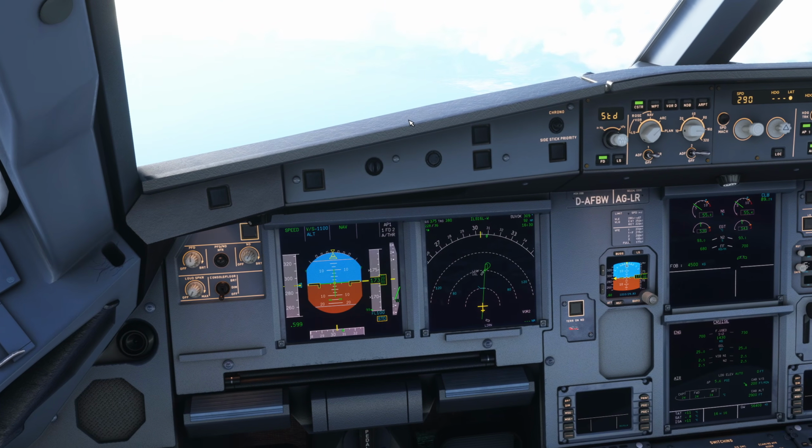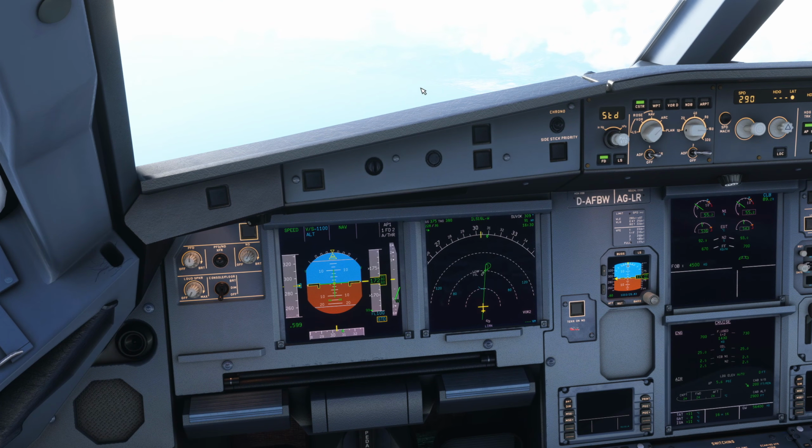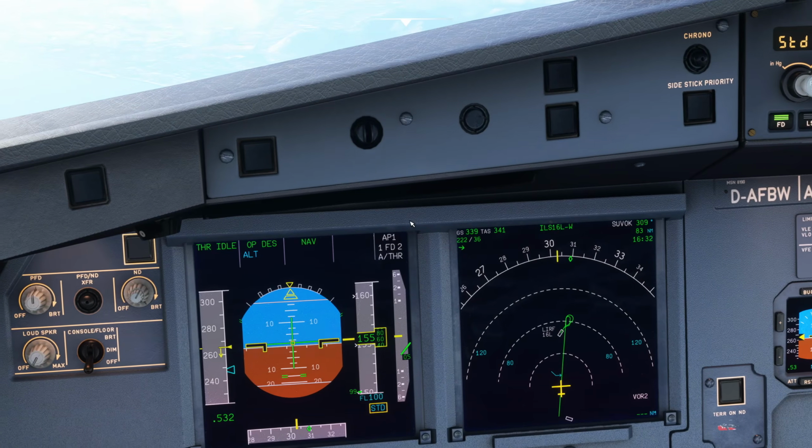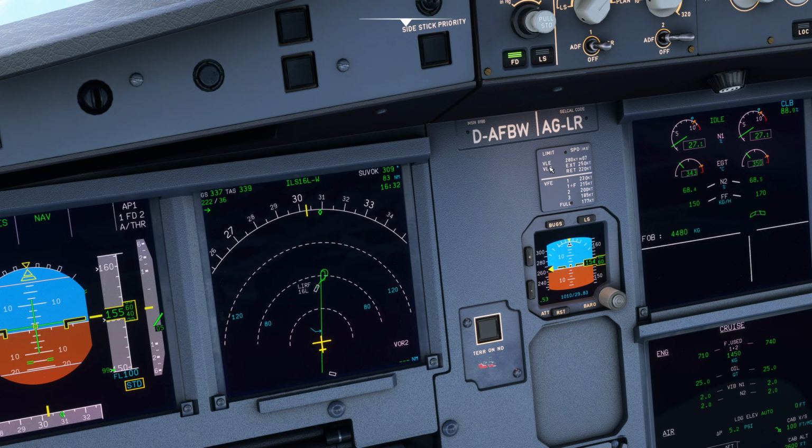So what I'm going to do now, just to show you what normally happens, is go down to flight level 100 as quickly as we can, and we'll lower the gear at a sensible speed to show you what the indications normally are. Right, so we're now low enough to lower the landing gear. The limitation is here, VLE, velocity with landing gear extended: 280 knots, Mach decimal 67.